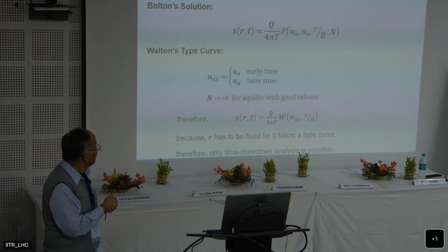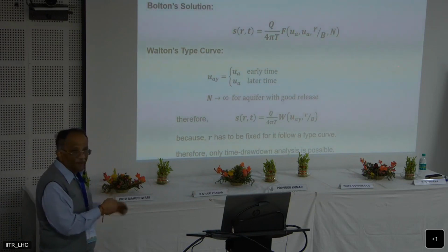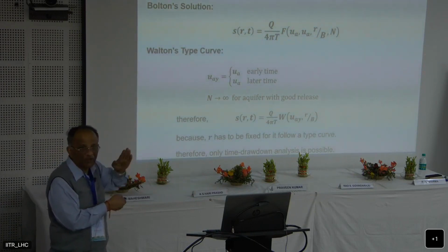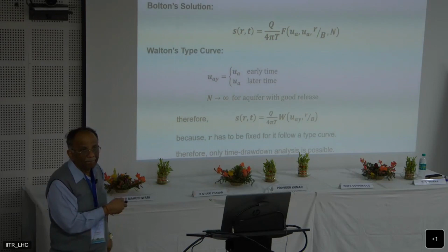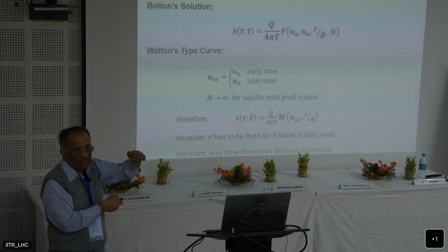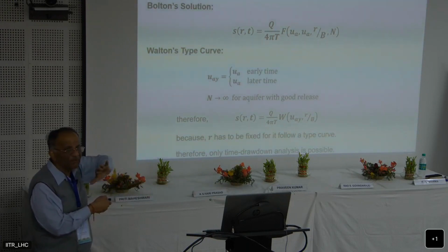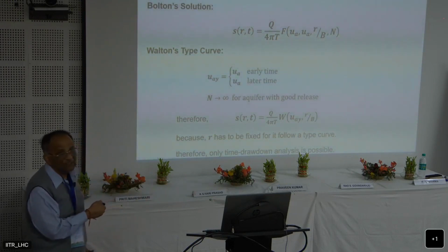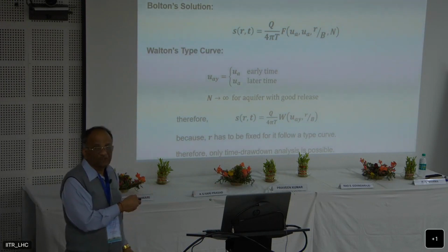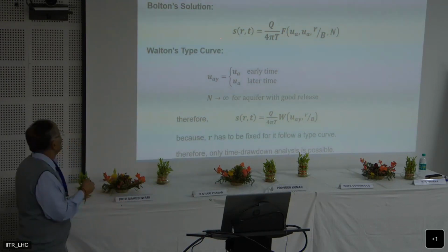As Professor Govindaraju showed you in one figure, at early time there is a very short increase in the drawdown. In the intermediate times, the rate of increase is quite less. This is what we call where the delayed drainage is contributing. Afterwards, once this delayed drainage is complete, there will be a rising curve. So to get all 3 segments of the pumping test, you have to run it for a considerably long time.